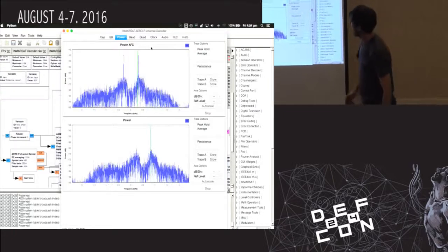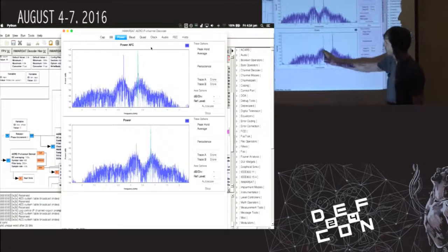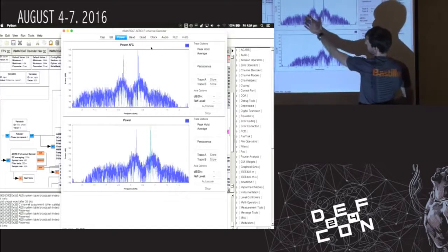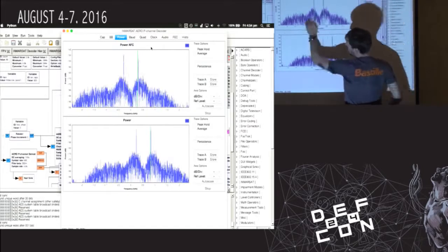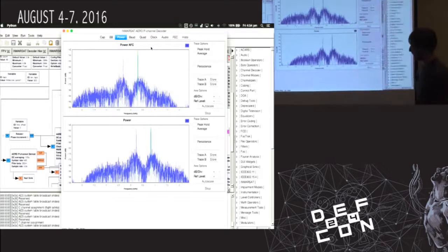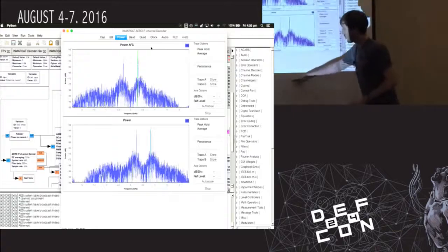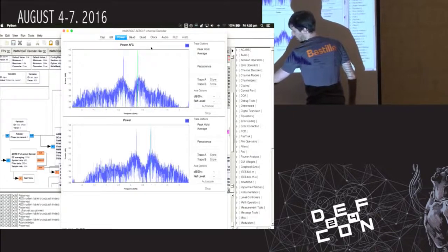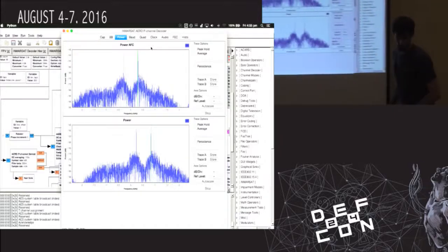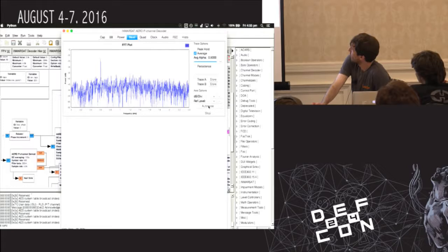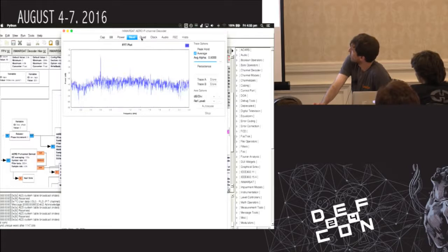So this is what's originally coming in. You can square it, and those peaks are still offset. Here, we've moved it back because we're showing what the output post rotator is, and that's nicely lined up around the center marker there. It's off the screen, unfortunately, but it actually has a little graphical text box that's telling you what the detected frequency offset is. Of course, we've got the baud rate there, and it's exactly at 600 as we expect.